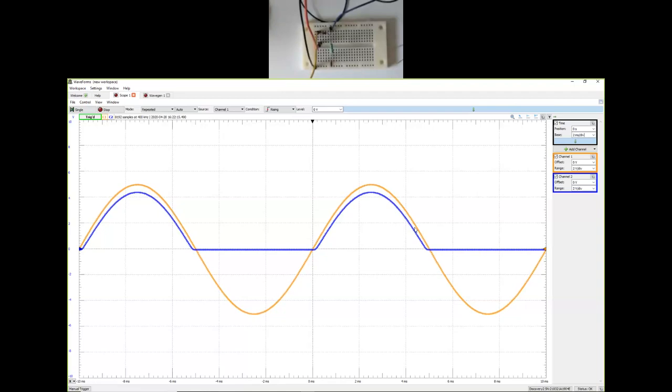So that's my half wave rectified output for a sine wave input. And in theory, the reasoning is the same. The average is going up. We are essentially eliminating the negative half cycles because no current flows through the diode when they are negative, when it is in the reverse biased region. So the underlying concepts are very similar. It's just that the shape of the graph is sinusoidal instead of a triangle wave.